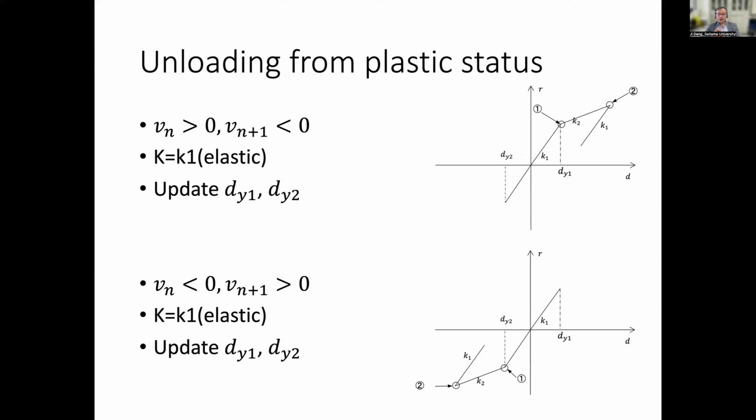Also, we need to update dy1 and dy2. I will explain why later: it is because we are using something called hardening rules. These hardening rules tell us how this elastic domain changes after loading. So we need to update dy1 and dy2 here.